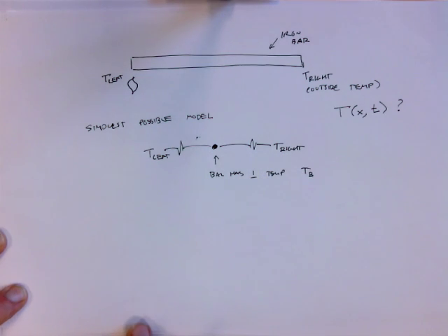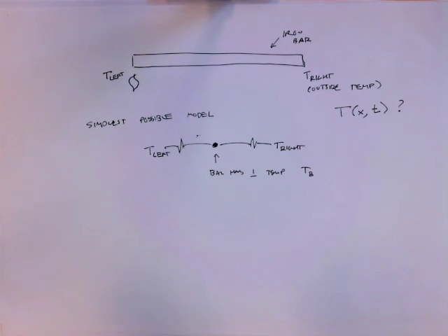Right? And Mark, why do you draw a resistor? Well, I draw a resistor because I seem to remember from things like ModCon and iSim and all the various versions that you could have resistors and capacitors and inductors. Why do you draw a resistor? I think it's because my background is electrical engineering, John. But it's also because we often talk about thermal resistance. And in the same way that an electrical resistor resists current, that is when you apply a certain voltage across it, there's a certain amount of current that flows, objects also have a thermal resistance. When you put a certain temperature difference across it, a certain amount of heat energy flows through the bar.